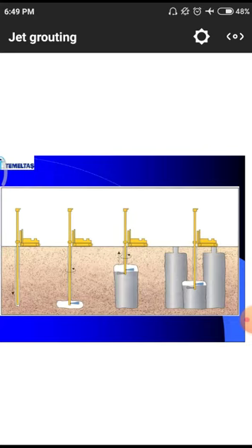In case of the fourth, there are a total of two holes. In between the holes, they are making another hole and filling it with this jet grouting material. Whenever we have a structure with cracks, we particularly have to observe these kinds of operations in dams.